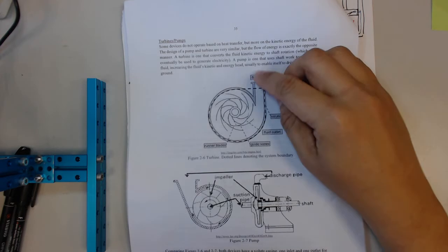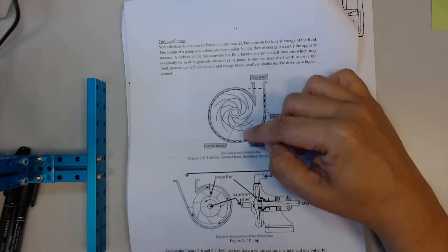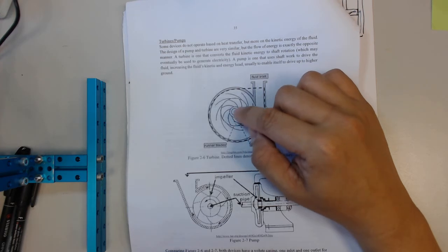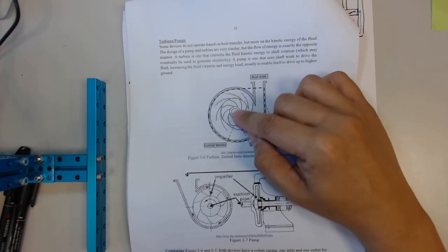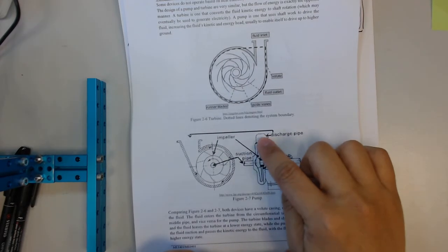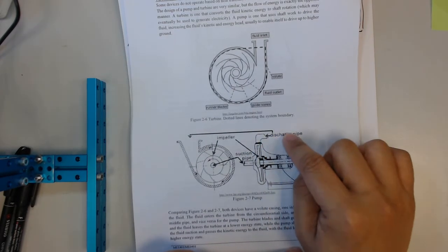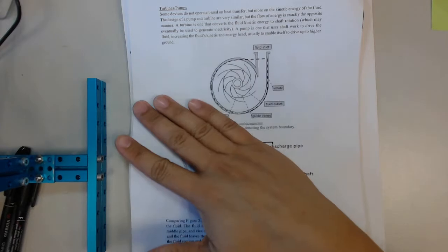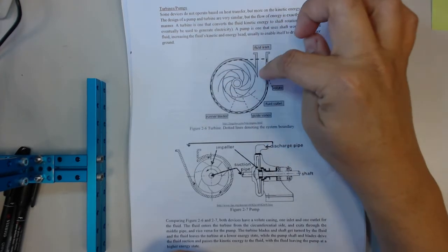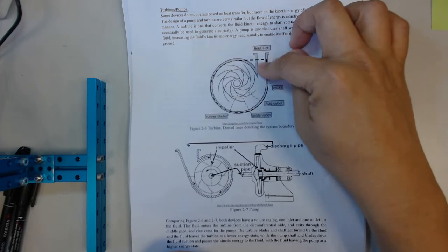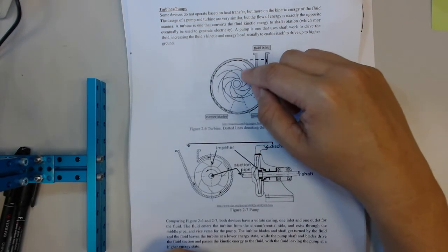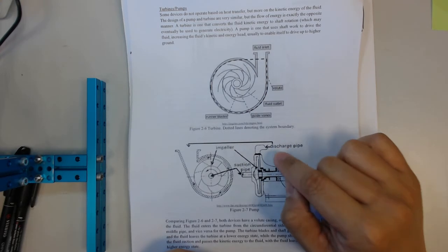You are going to have a certain fluid coming in, and then you're going to have rotating blades that will force the fluid that goes in to go out in another channel. If you look at the other cross section, the fluid will actually come out from here. So the main difference between pumps and turbines is this: the pump will actually provide the energy to the fluid. Means when the fluid comes in, it is at a lower energy state, and that is where it will get pushed by the pump blades and exit in a higher energy state.